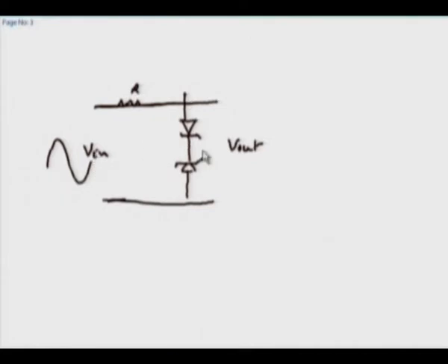Now, if you use a sinusoid kind of back to back like this, and if your input is sine, assume that we have a 10 sin omega t here, and we assume these to be 6 volt sinusoids, and if you assume the forward diode drop to be about 0.6 volts, then what you would get at the output would be a kind of clipped sine wave with a plus 6.6 and a minus 6.6.